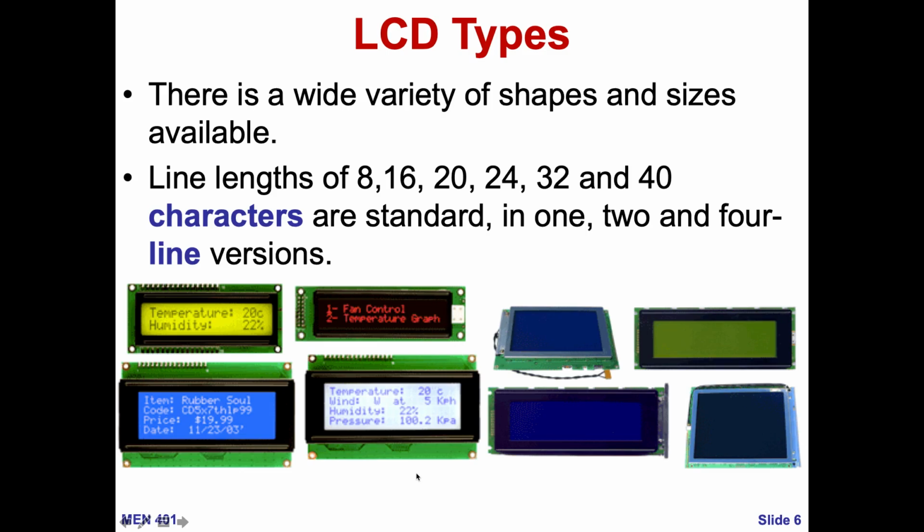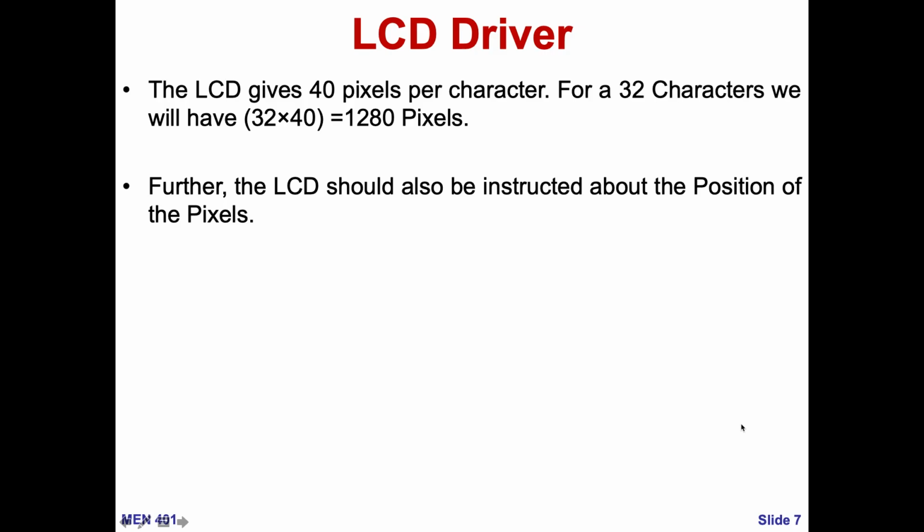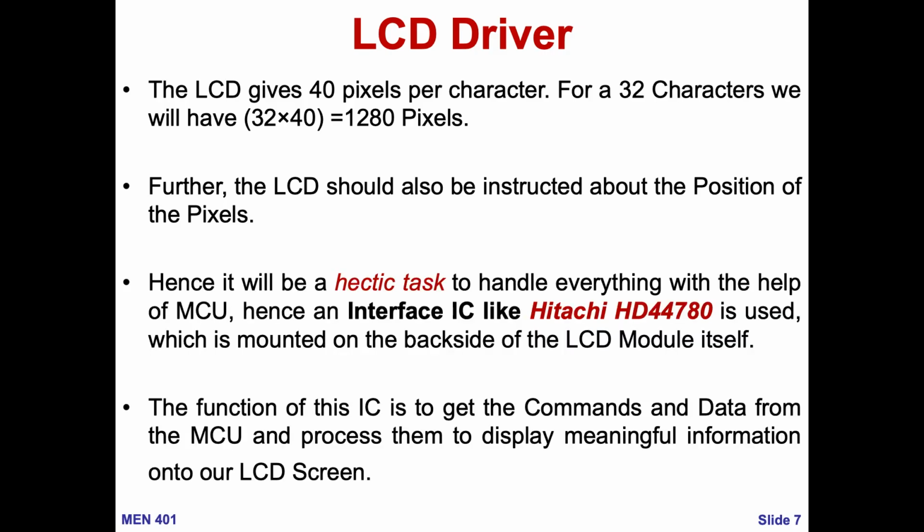Okay, so here is the problem: communicating from a microcontroller directly to an LCD is not easy. Because every pixel, and we will see later on that every character has around 40 pixels, should have a current. So really, it's not very easy. This is why in the back of the LCD there is what we call a driver. As I said, it's a hectic task to handle everything, so we need a driver.